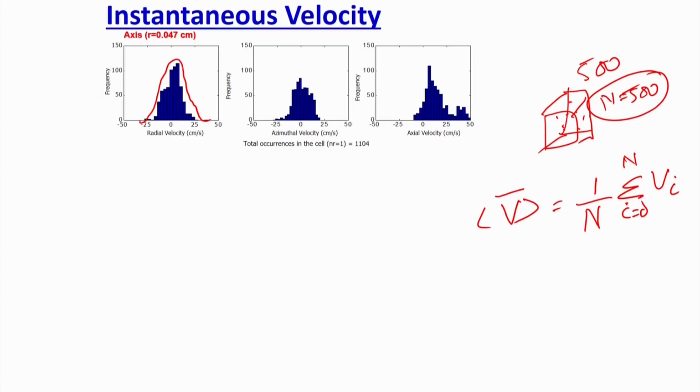So the particle velocity will be different. The mean velocity, which we talk about, is just a statistical quantity. Ideally you never see the mean velocity; sometimes you see somewhere plus or somewhere minus. How much plus, how much minus, that information is also needed if you want to do a proper scale-up, if you want to really understand the system. Like in this case, the mean velocity will come in the range of around 1 or 2 or 5 centimeter per second, while the instantaneous velocity is changing by 20 centimeter per second plus or minus. So, a wide distribution.